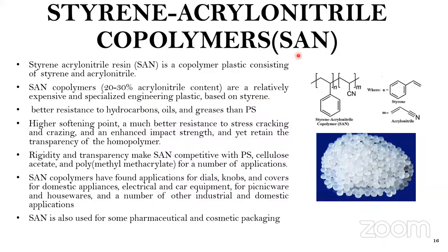These SANs are quite costly and only produced on special demand. They have a much better resistance to hydrocarbons, oils, or greases than PC. As compared to polystyrene, these SANs have a much better resistance to chemicals.